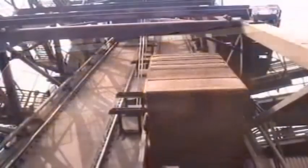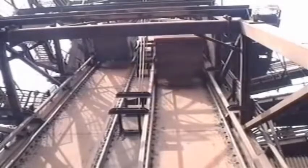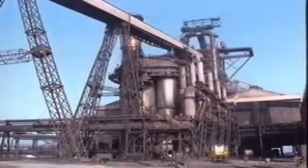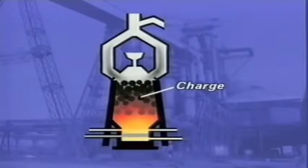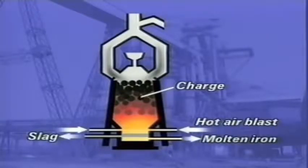Sinter and extra coke, ore and limestone, known as the charge, are lifted to the top of the blast furnace. The Scunthorpe furnaces are fed by skips. Furnaces run continuously day and night. The blast furnace is a steel tower up to 40 metres high, lined with heat-resistant brick. The charge is delivered into the top of the furnace. Hot air is blown in at the bottom. Molten iron is produced, and slag.